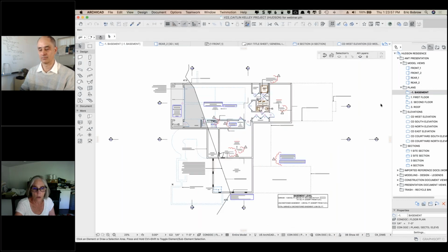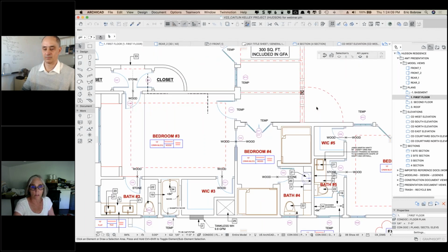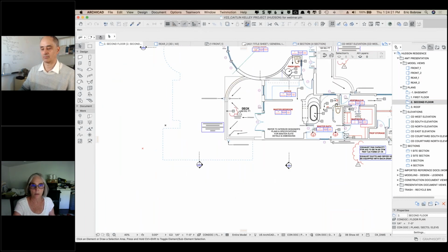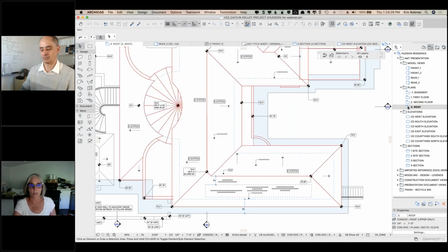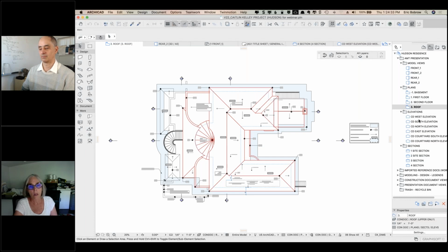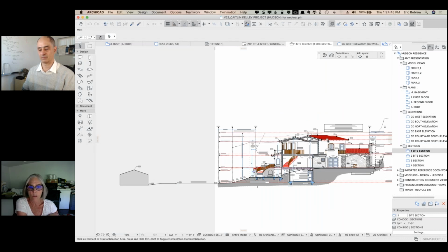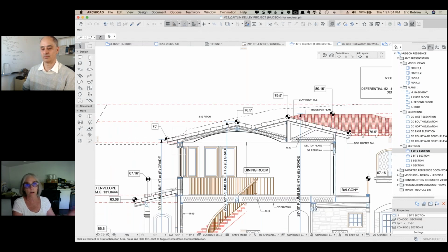Being in La Jolla and that close to the ocean, it was quite involved in terms of all the data that needed to be really, really accurate for the different constraints that the jurisdiction has imposed upon development in La Jolla. There was the coastal review, the La Jolla design review, the city's review process, making sure you're adhering to all the height limits, and with a basement, you can't go over existing grades with the heights. So the drawings actually reflect a lot of this data in terms of what needed to be shown to the city, that we're not exceeding heights, and that certain parts of the basement are being counted toward the floor area ratios and things like that.